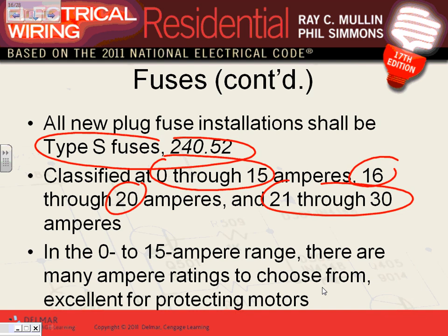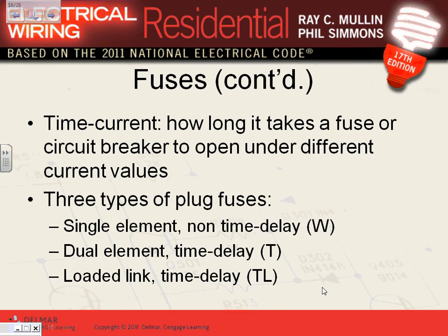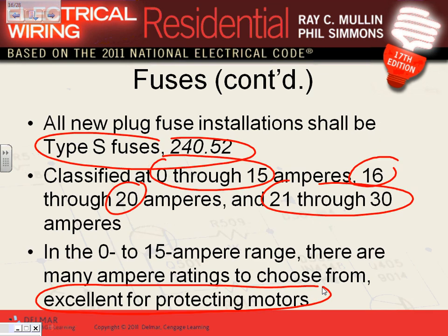Any question? What we suggest here, this is excellent for protecting motors. We use them in our motors. We're talking about single phase residential. They use them sometimes, guys, with the garage door opener. They have in the garage door opener box a fuse, and they use it as a supplemental overcurrent protection device to the garage door opener. Commonly used. So you put a 10 amp fuse to protect the motor. Any question about the fuses? This type of fuses, the plug-in fuses.